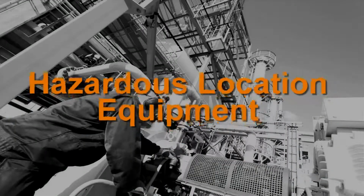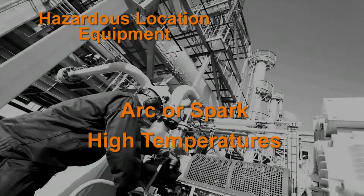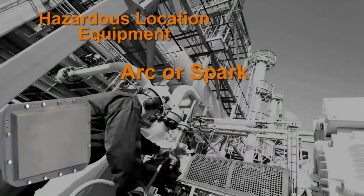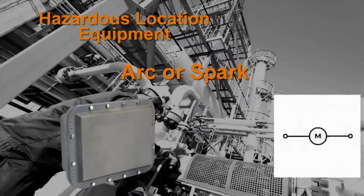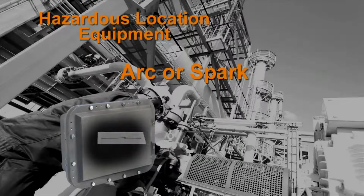The 3 predominant methods are arc or spark, high temperatures, and electrical equipment failures. Arcs and sparks are produced by normal operation of equipment like motor starters, contactors, and switches. As the name describes, these types of devices create arcs that could potentially ignite a hazardous location atmosphere.